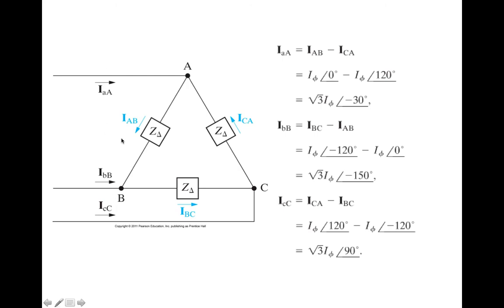It's like this is in a black box. If I replace this with an equivalent circuit, my line currents, my voltages between the lines are going to be the same. That's the definition of terminal pair equivalence. So you can convert to Y configuration, you can convert back to delta configuration. These currents going into that black box and the voltages between the terminals coming out of the black box are going to remain the same.